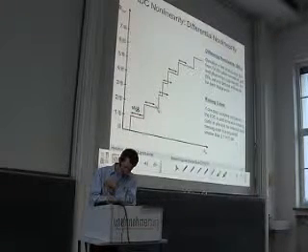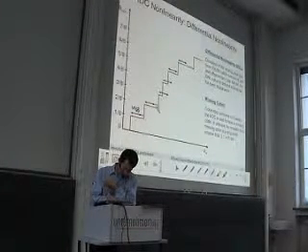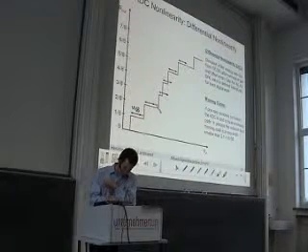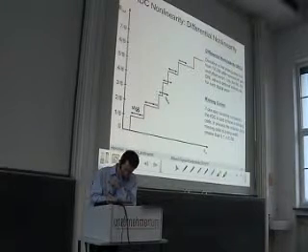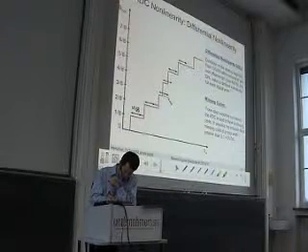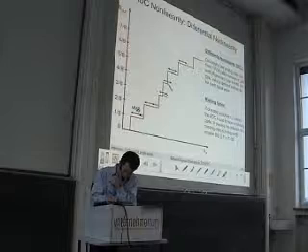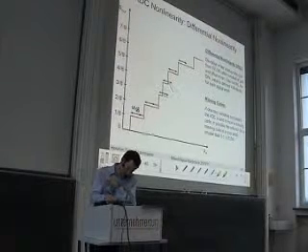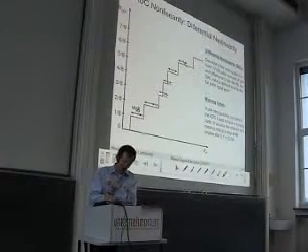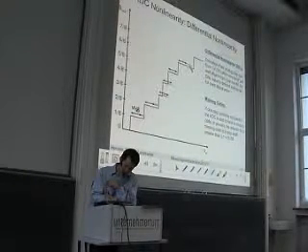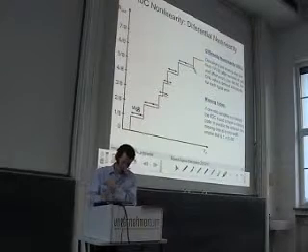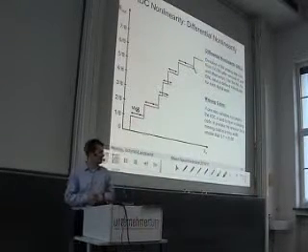So here, for the first two steps, you can see that the differential non-linearity is positive. The step is too large. Then here we can see the step is too small, so we get a negative differential non-linearity. The next one is more or less ideal. And here again we have one which is too wide, so we get a positive differential non-linearity.